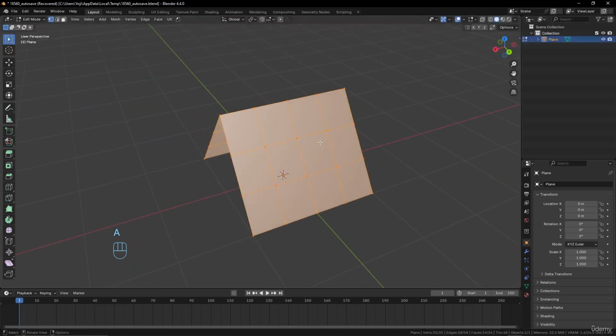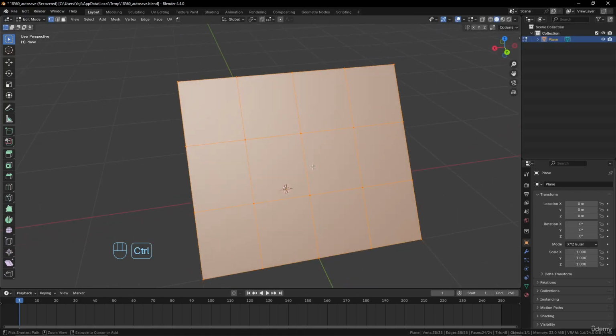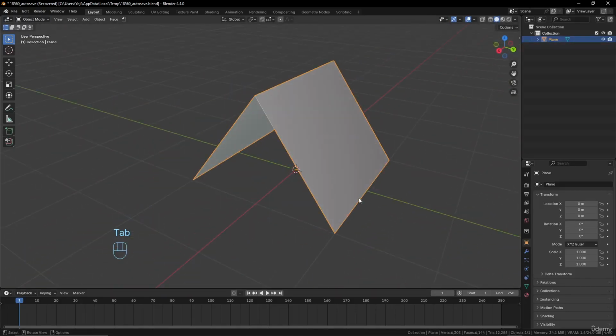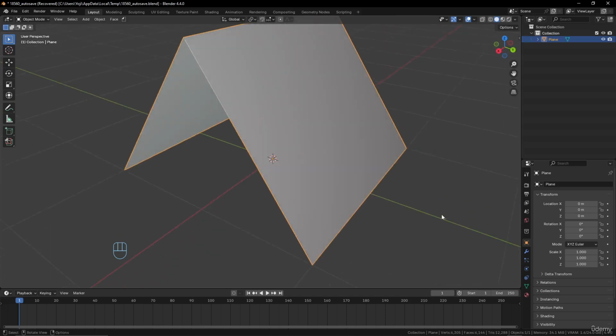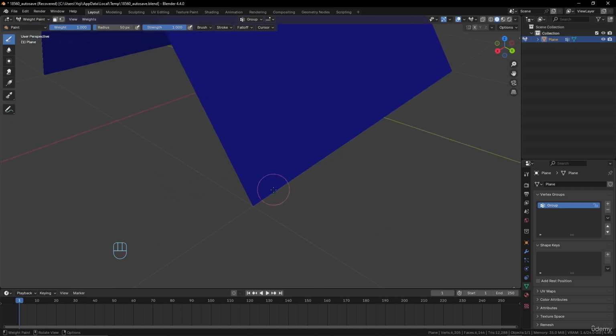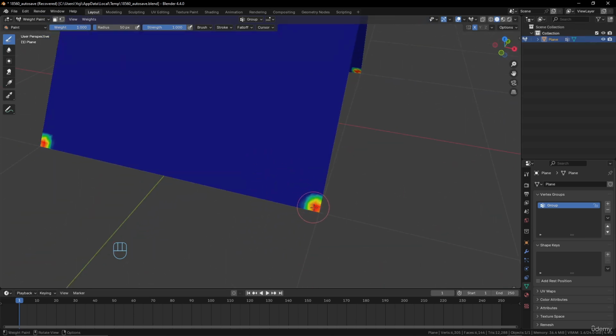And now you can subdivide it finally to not have these stretched faces. And now just with right click and subdivide, I will have enough subdivision to work with, okay? So now I will just want to add more groups here, and it will be over there that I will play with that. So let's say you will have a group here. You can play with X symmetry if needed, like this. You don't have to paint the other side, just like so.